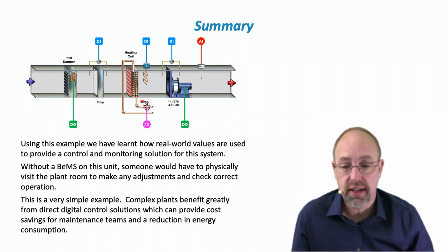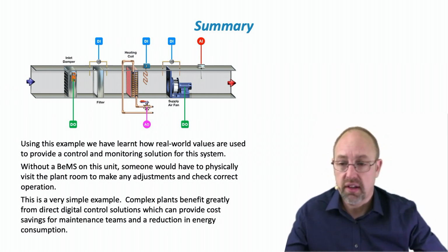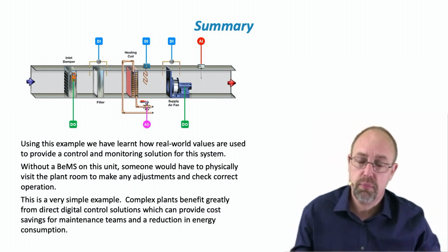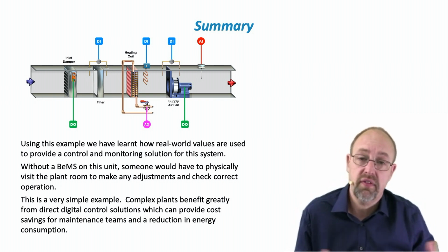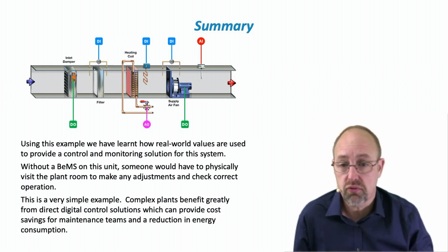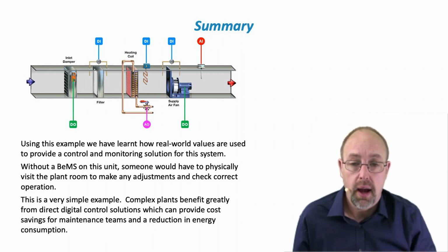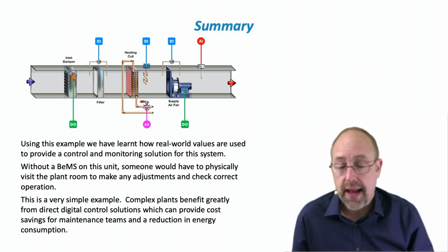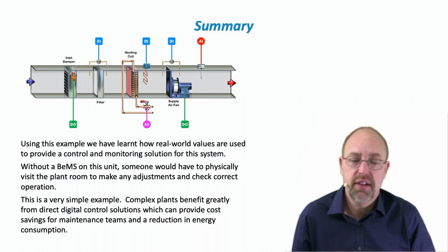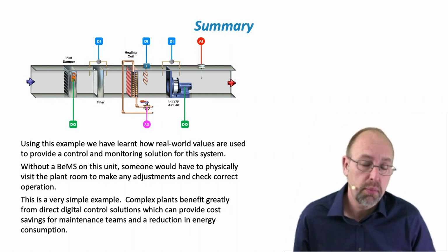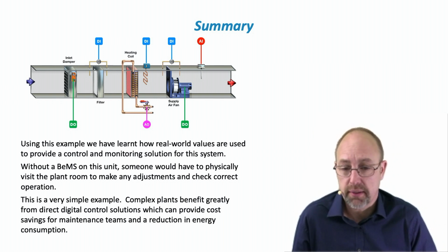For those of you who are working in admin roles, etc., you've probably seen dozens of controllers going into panels going out to site. This is how they fit in to small systems like this, to very large, complex systems with recirc and heat recovery, etc. But it's all based on the same principle. You have analog and digital inputs, analog and digital outputs, and you have a control application, which your excellent and brilliant value engineers are creating in the middle and then going out to site and commissioning.